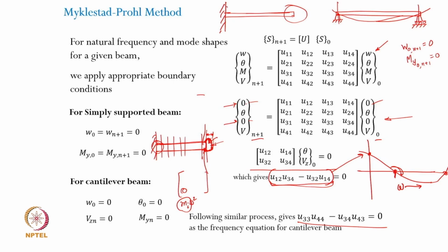So if your properties like the cross sectional dimensions are continuously changing, as I said, that is very typical of a cantilever beam, that is very typical of the blades on the gas and steam turbines. You can discretize this into several segments, and each segment's cross sectional properties can be assumed constant in the segment, right? Now there would be obviously inaccuracies, because depending upon how wide the segment is, your properties are going to be an approximate estimate of the entire segment, because you are averaging it out, right?